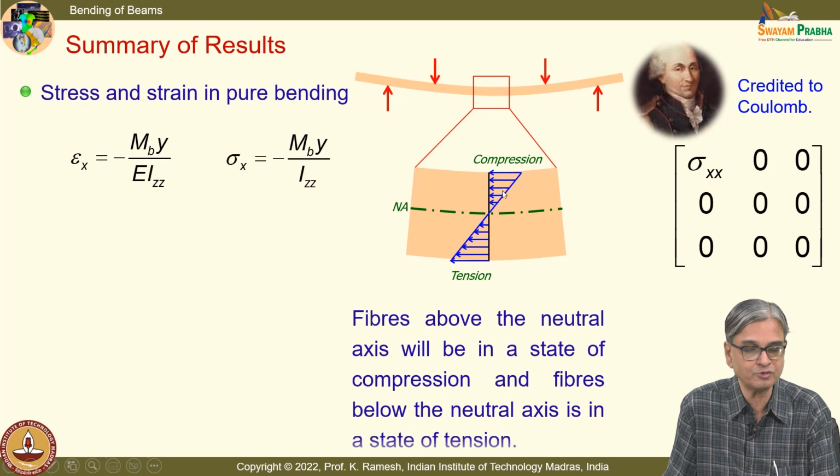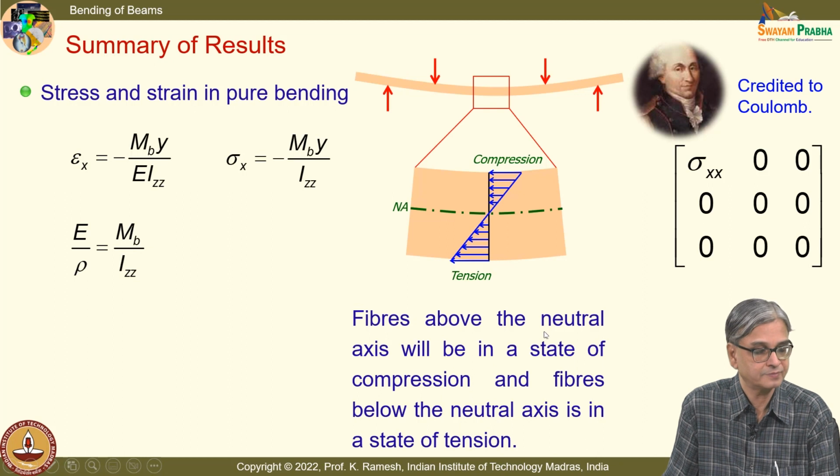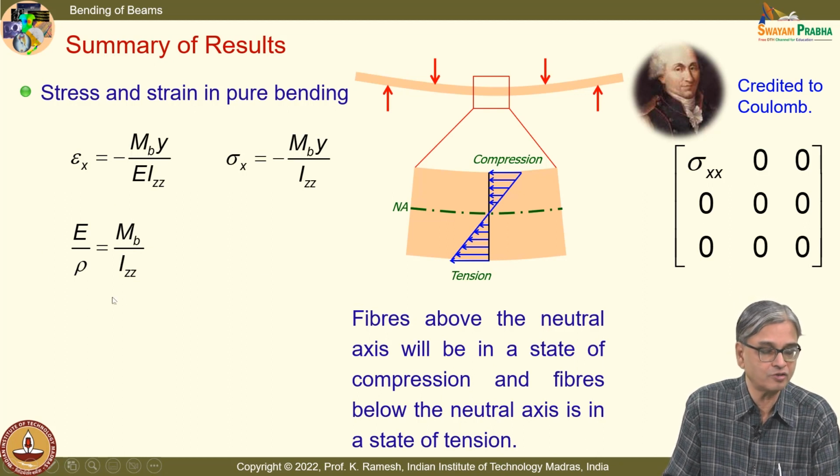So, fibers above the neutral axis, when I apply a positive bending moment, are subjected to compression. Below the neutral axis, they are subjected to tension. And from the equilibrium consideration, we have also related the curvature to the bending moment.